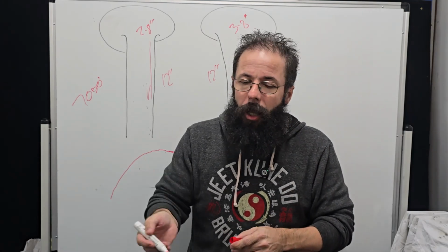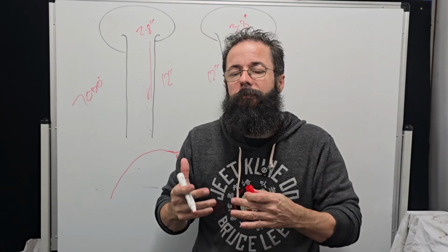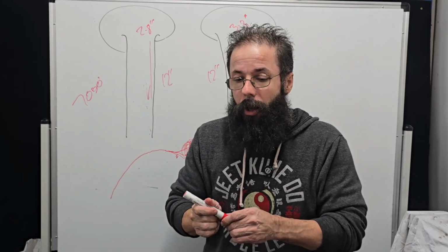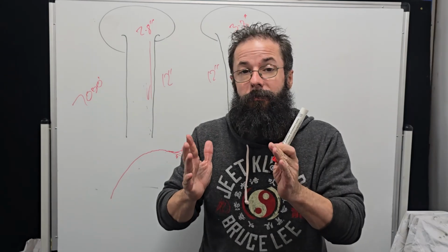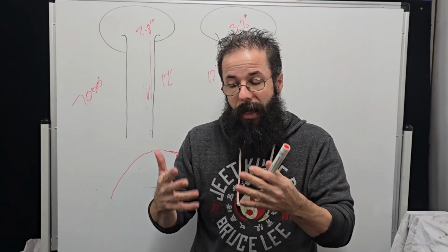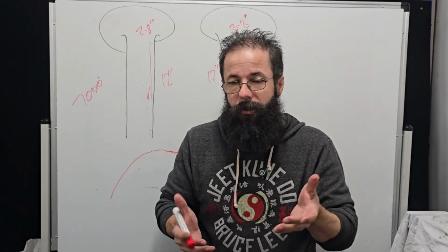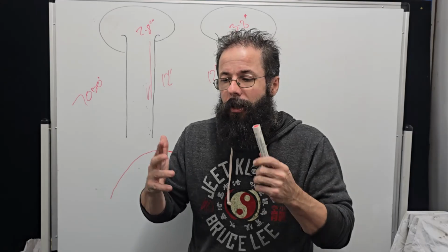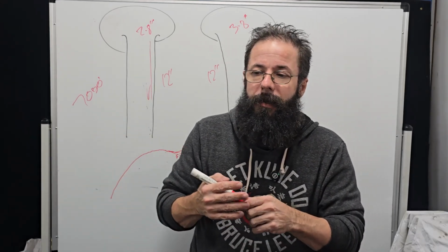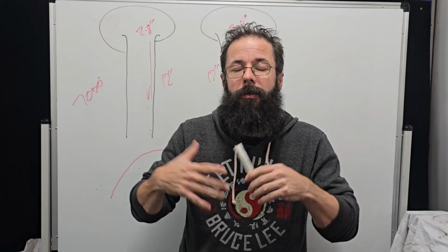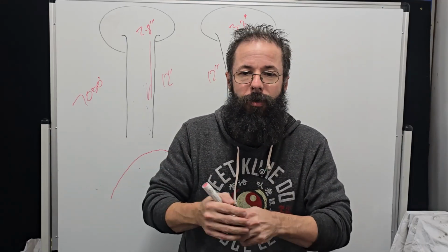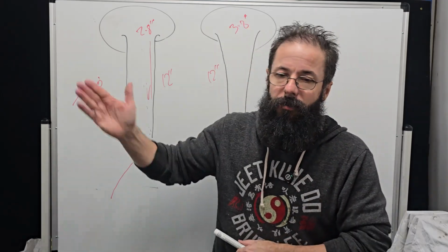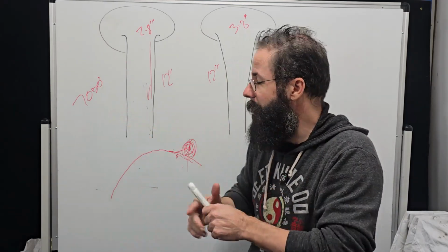So a lot of guys are really just getting poor feedback on the dyno because they're using a parallel runner, not a tapered runner, and they're not harmonizing the two mechanisms that they're trying to make benefit out of. And a lot of OEM manifolds are like this because they're just very easy to cast. They just do them one diameter, and they're more torque related. Again, a lot of people look at OEM, but you've got to remember they're really low range engines because they're emission standard. They've got to cruise along at 2,000 and make emissions, where a race engine doesn't. You know, it sort of starts for us at 4,000 or 5,000, 6,000 depending on peak RPM.